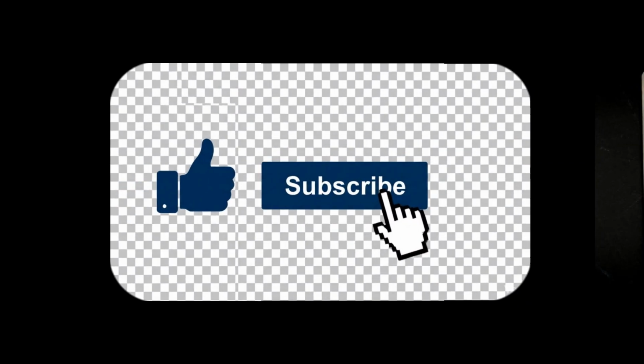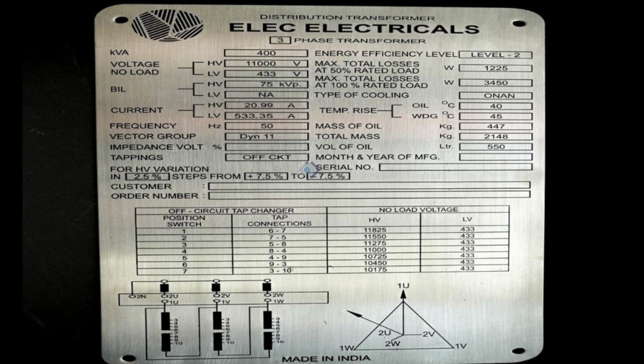Let's get into it. Now we are looking at a real transformer nameplate. This is a 400 kVA 3-phase distribution transformer made by Elec. Everything we have studied in this video appears right here on this plate. Starting at the top, the rating is 400 kVA. That stands for kilovolt-amperes, the maximum apparent power the transformer can deliver continuously. Think of it as the size of the transformer.